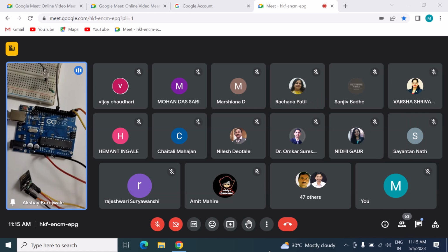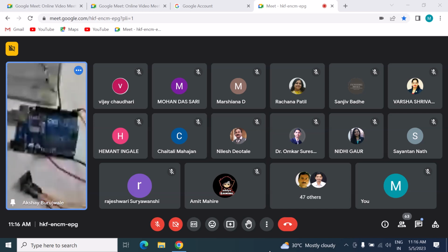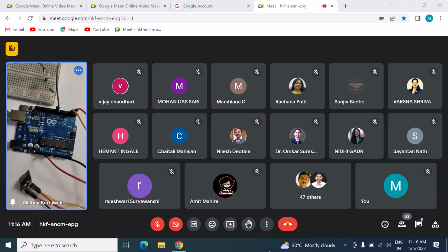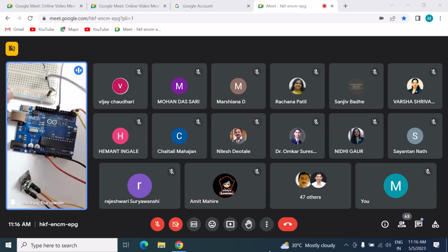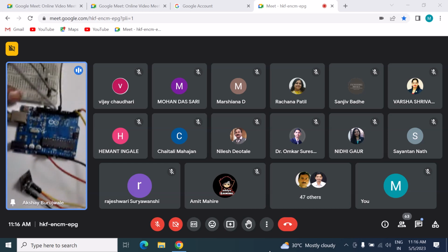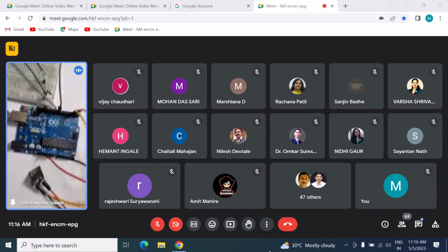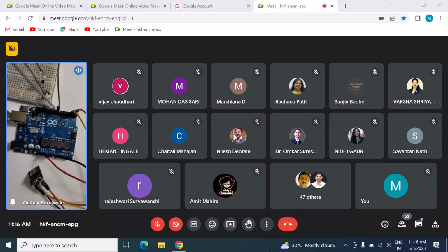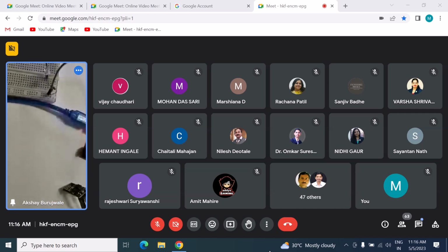Male to male. Okay, I get it, the ground wire. So it is connected here, and again to the ground. Okay, so my connection is completed. Here is my Bluetooth Wi-Fi module, and the LED is connected. The Arduino board is connected. Now I'm going to upload that code, whatever we have generated through remote XY.